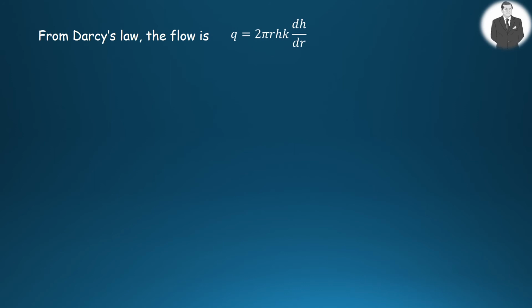From Darcy's law, the flow of water can be calculated as 2 times pi times r times h, which is the area, times k, which is permeability, times dh over dr, which is the hydraulic gradient.